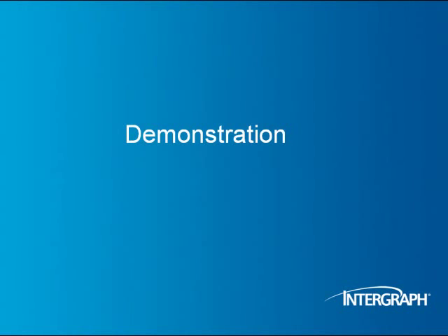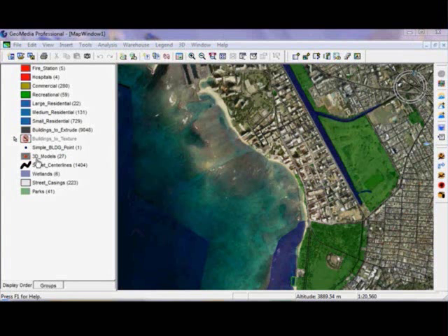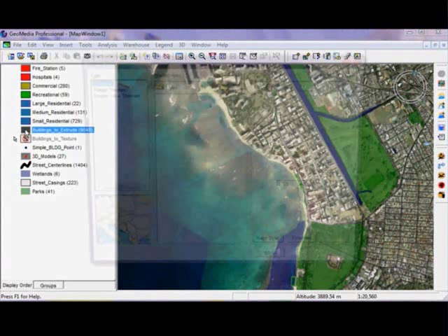So I'll give you a brief walkthrough of what I've been talking about. What we're seeing here is a number of feature classes, and I'm just going to show you a couple, but I think that'll give you the flavor for how this will work. And I've got one that I've called buildings to extrude, so I just simply have height information for those buildings, so I'm going to do a simple extrusion. And then I've got some residential, commercial, recreational feature classes, as well as some hospitals and fire stations.